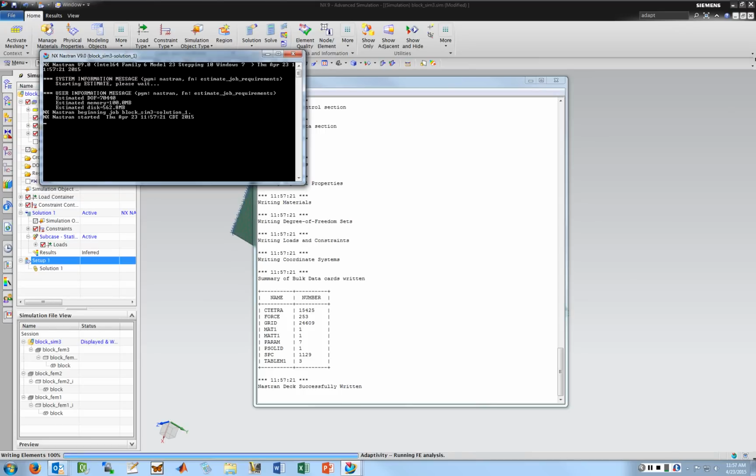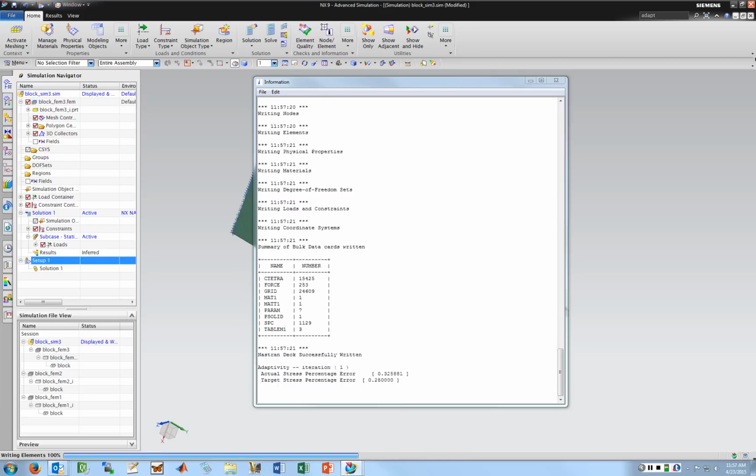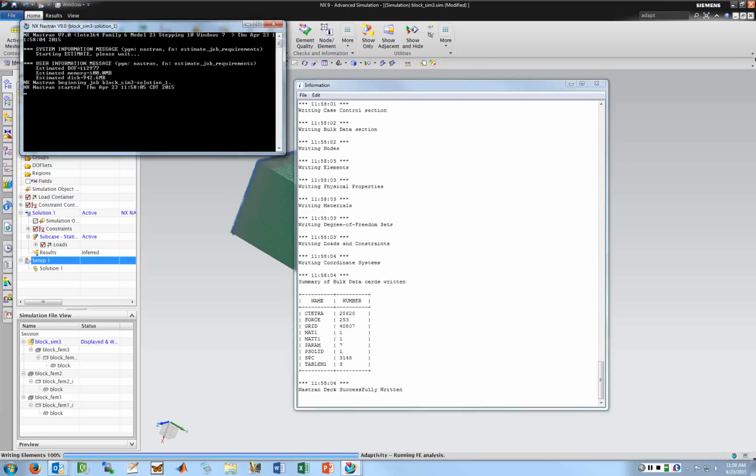So it's very helpful. It's not the end all be all of FEA. I can't just run this and exactly trust the results, because what you'll find in this particular situation, so you can see now it's a little bit better, and you can actually see the refinement here, is it's going to keep refining and refining and refining because of the way this fixed constraint works here in the practically loaded part. You're going to end up seeing little bitty peak stresses somewhere in here that are really ridiculously high that you really can't rely on. It's just because in the real world you never can get a constraint that works exactly like this. So it's going to start refining away here, but just right away from those really highly loaded nodes, which is what you'll see here in a bit, everything else is going to be almost exactly what it's supposed to be, which is the load basically divided by the area in square inches.